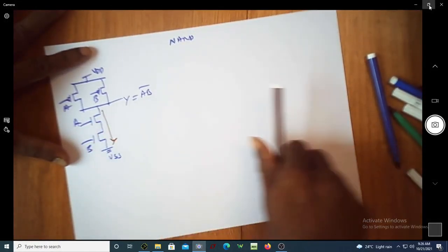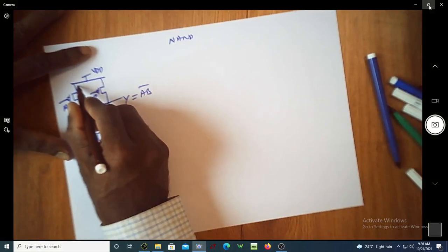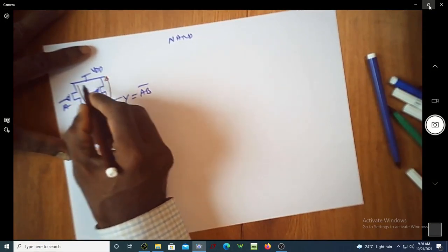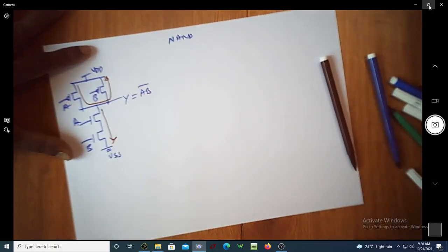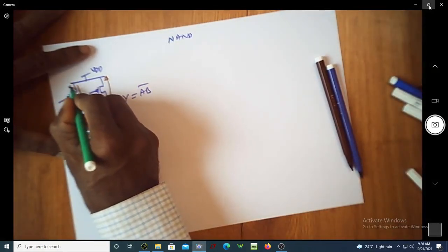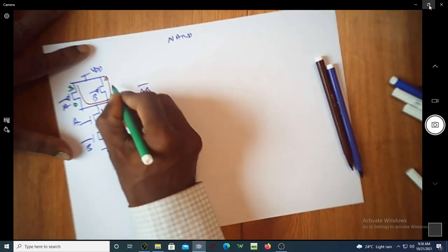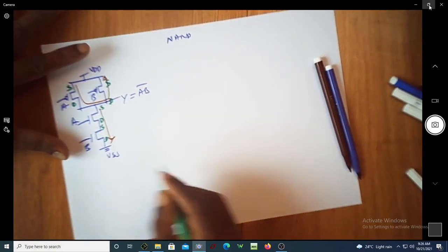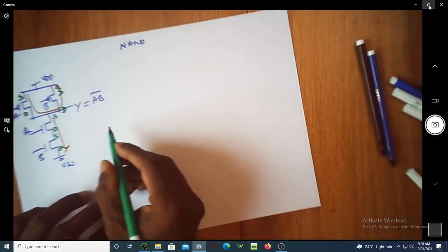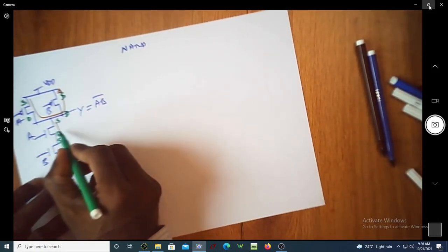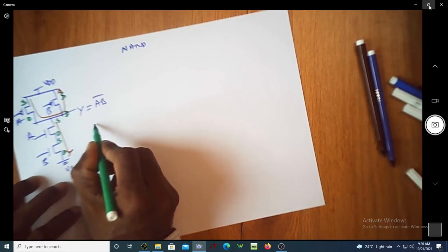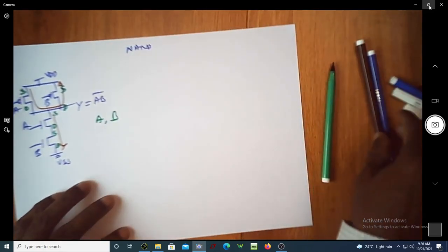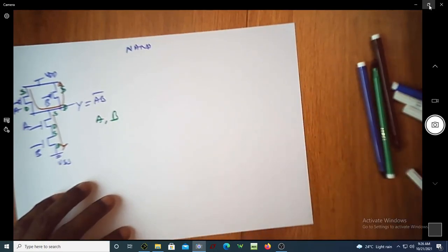So this is Euler's path, which is actually starting from a point and going back to the same point. You can see, if you start naming the source and drains, this is source, drain, drain, source. This is actually source, drain, source, drain. So now the input configuration is first A and then B, and you have an N well.